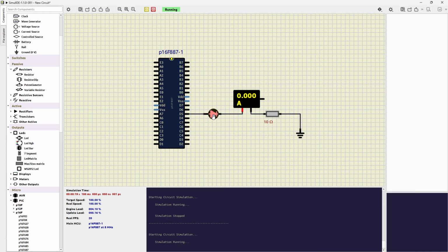Not dangerous at all, but basically your LED will be burned out eventually as time goes by, because of the high current that it is managing. So in order to keep this LED alive, it should work with a range from 10 to 20 milliamperes.